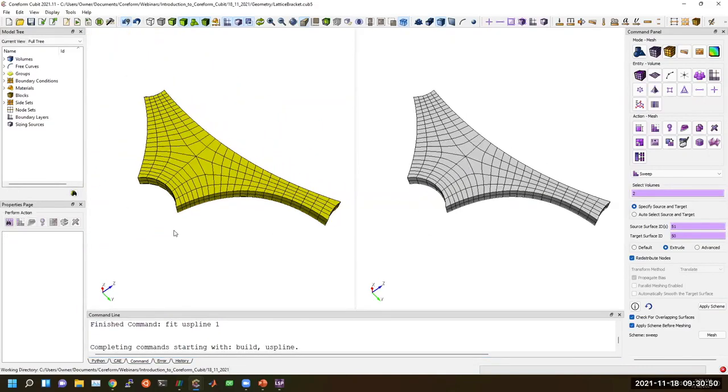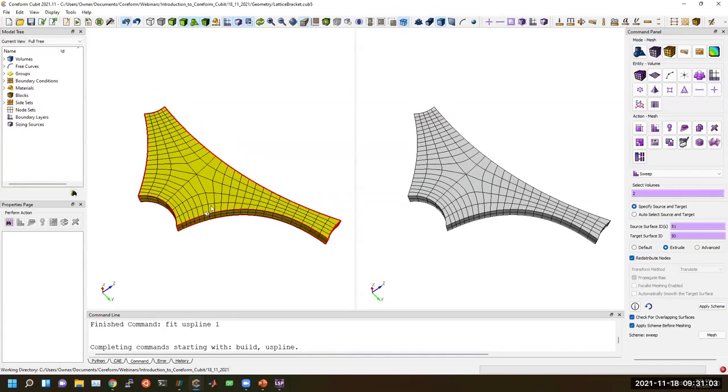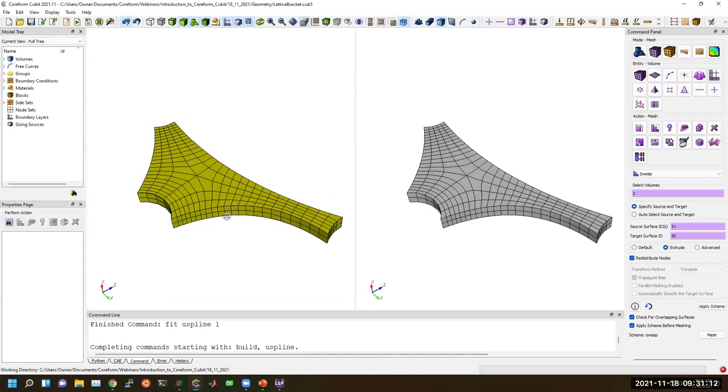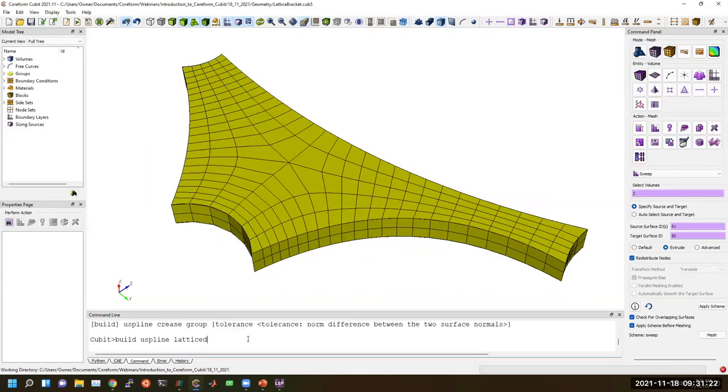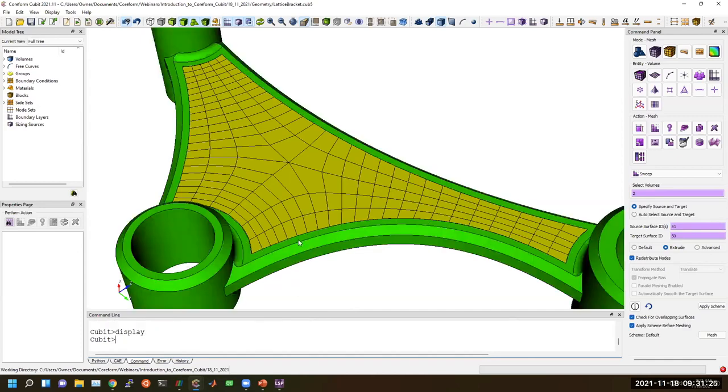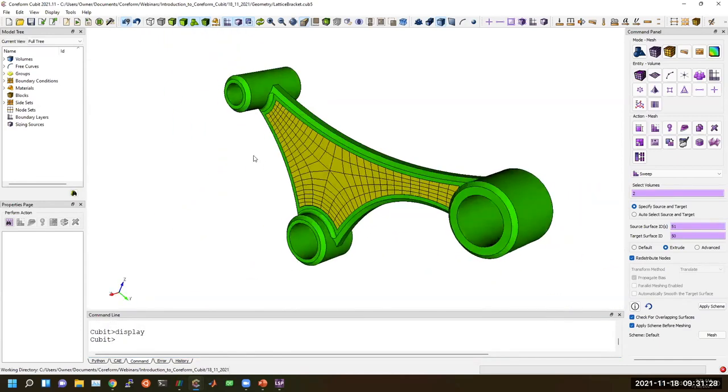What's unique about this representation, however, is that you can use this background mesh within a model-based enterprise to define your lattice without actually having to render your lattice structure. So it's a well-known phenomenon that pulling in hundreds of thousands of unit cells into a CAD modeling tool when they're stored as an STL format can oftentimes crash your CAD modeler. And so instead we can incorporate these meshes within a model-based enterprise, and it represents your lattice structure with a lot less hardware requirements.